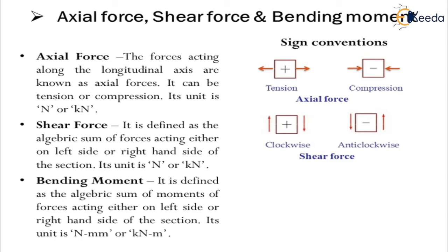The other force is bending moment. It is defined as the algebraic sum of moments of forces acting on left hand side or right hand side of the section. Its unit is Newton mm or kilonewton meter.